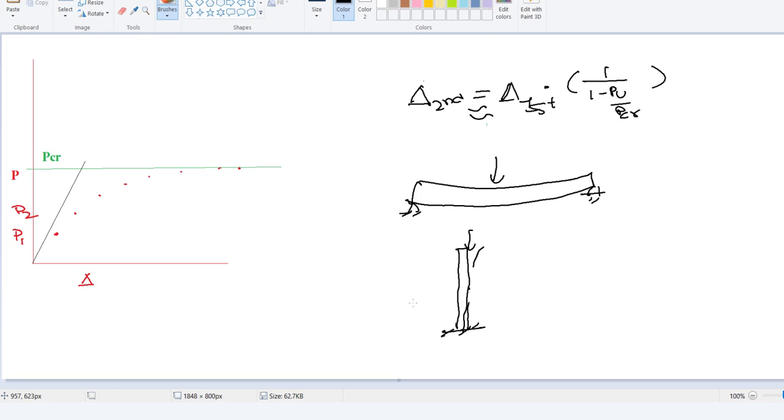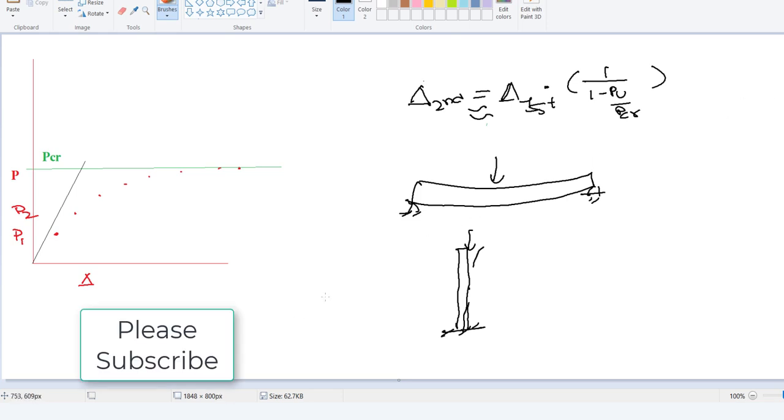In the next session, we would see some advanced understanding of how to solve the P-delta analysis in one step. We call it the KG matrix method. And this is the basis for the buckling analysis. The buckling analysis has also got two different approaches. One is the step by step, which is nothing but following this pattern like the one that we have just discussed here. And another is straightforward, we call it the eigenvalue buckling solution. We will just create a single equation from where we can solve the buckling value problem or the eigen problem and determine the buckling factor and the buckling load.